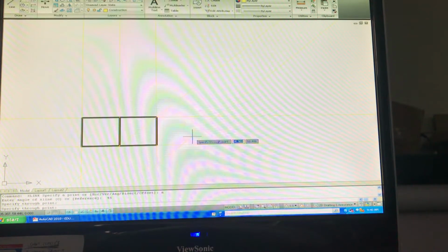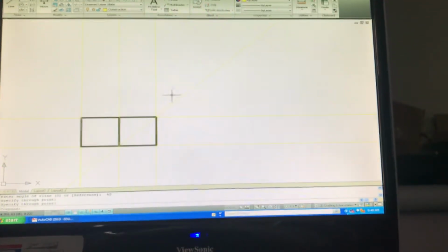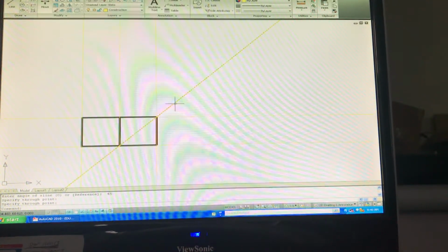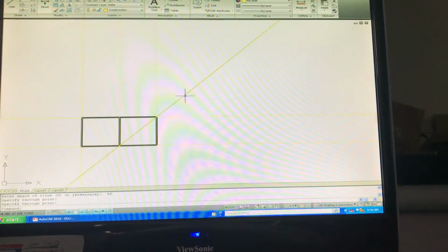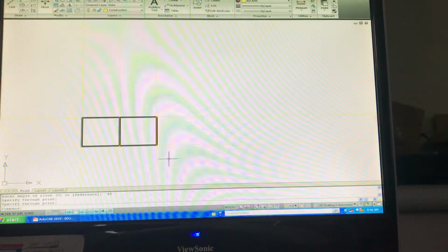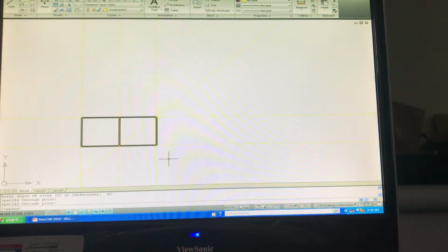And I have a 45-degree miter line going off of this point right here. Right? So those are all the construction lines I need off of my front view. That makes sense from what you guys did by hand, right?